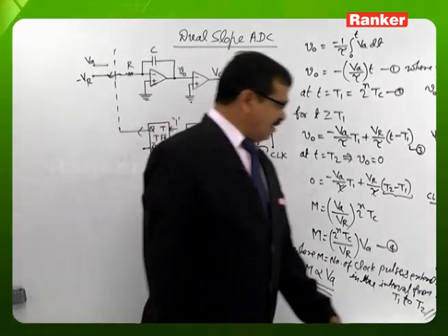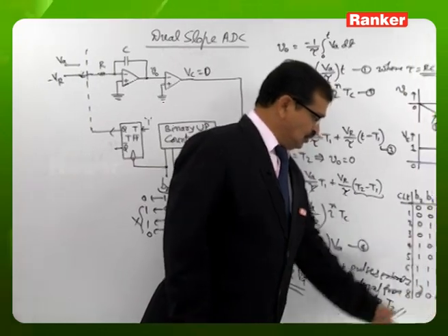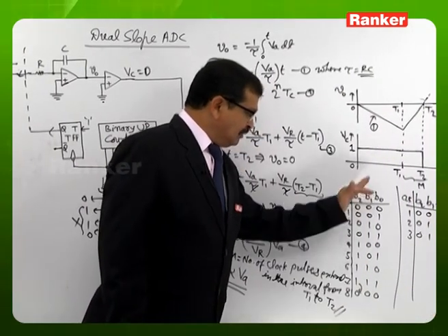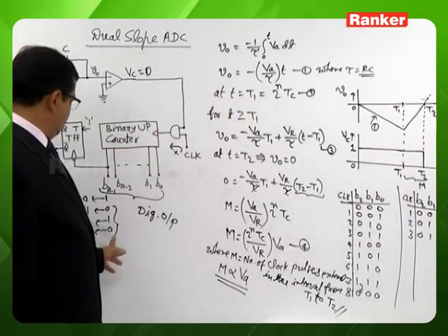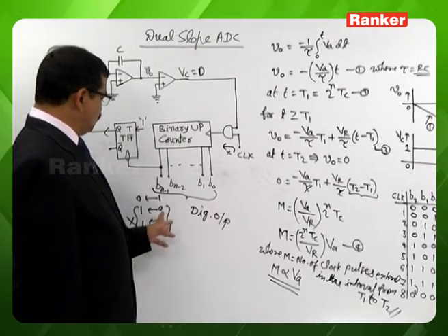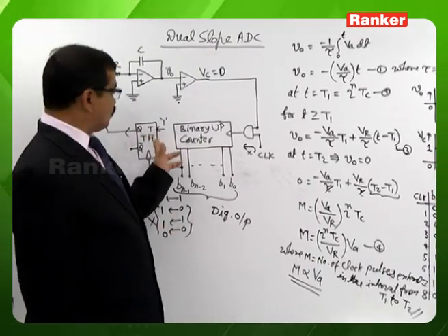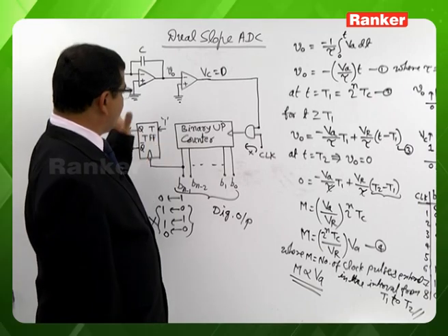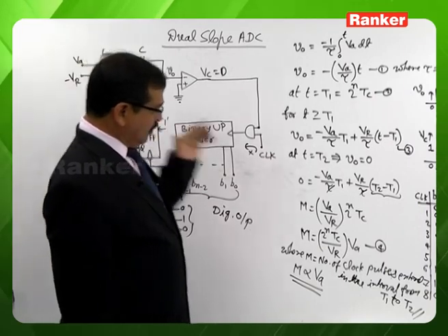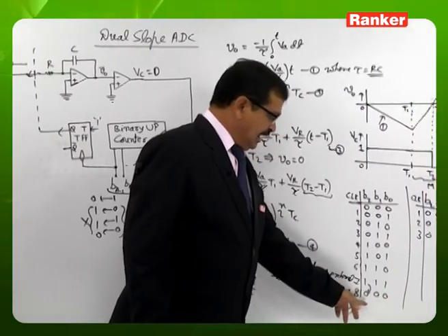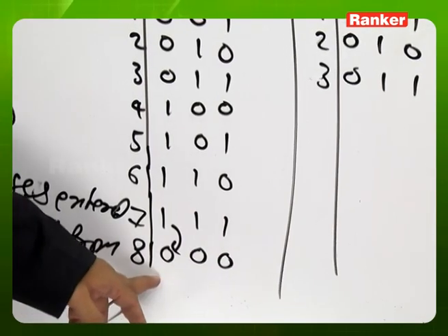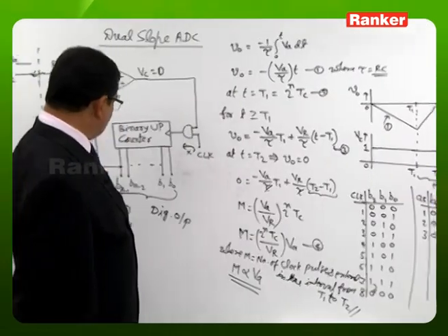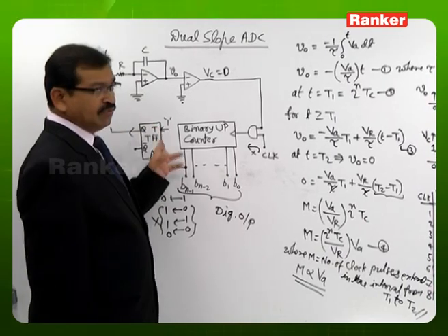Until it is not coming to 0, 0, 0, the change on the MSB bit will be either 0 to 0, 1 to 1, or 0 to 1. These are not coming as an effective clock to the T flip-flop, so the T flip-flop was not able to toggle until 0, 0, 0. As and when it gets 0, 0, 0, considering the 3-bit case, the MSB is changing 1 to 0, so the T flip-flop is going to toggle.